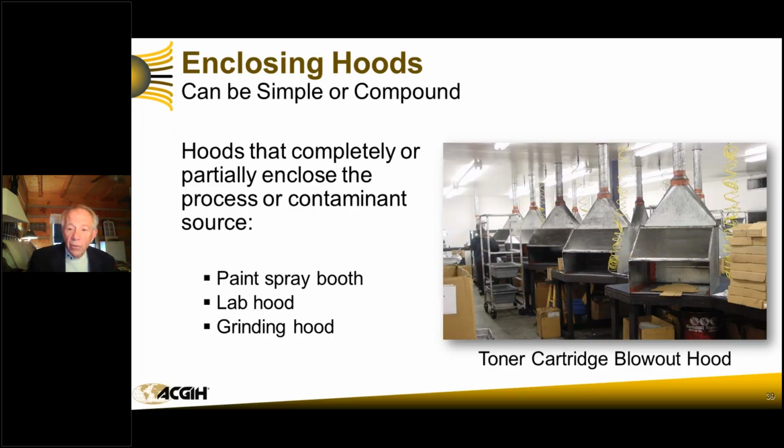So what we were able to do is we constructed a hood made out of cardboard. We put a small fan on the backside of it, and we found out that by sticking their hands inside here with the compressed air gun, they could put it in there, face the slot of the cartridge slot towards the backside, and when they made a ton of smoke or dust come out, it was all projected up in this direction. This is an area where they can view, so they can see there is a light inside, so that they can watch and see what they're doing.